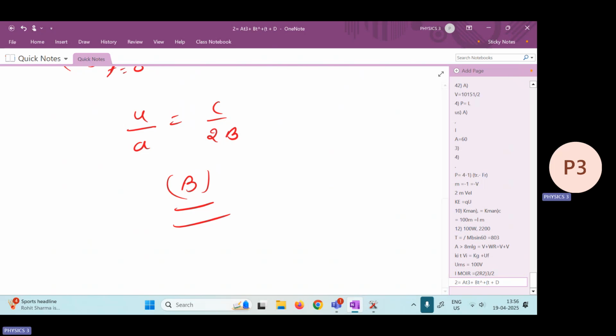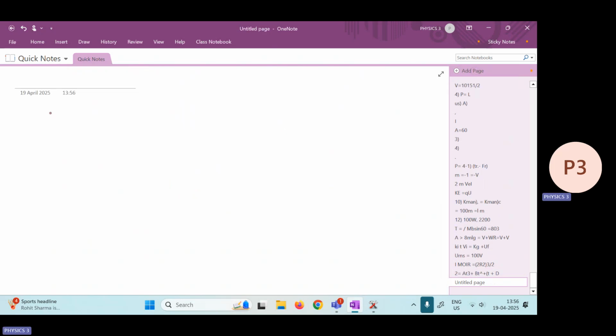Okay, now let's go to the next question, the 19th question. We have been given a circuit, and we are asked which logic gate the circuit diagram shown here corresponds to. Okay, so if we draw all the possibilities, the truth table here, it will be like 0, 0, 0, 1, 1, 0, 1, 1. So if we consider the OR gate, then this will be 0,